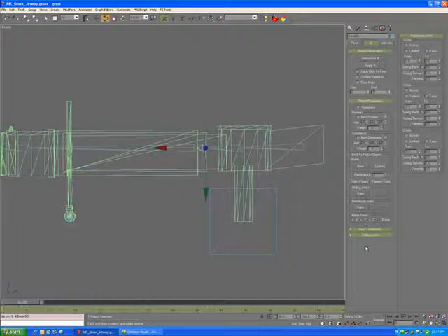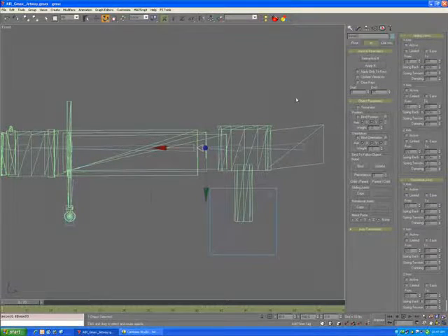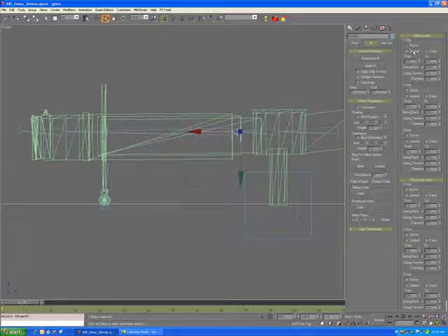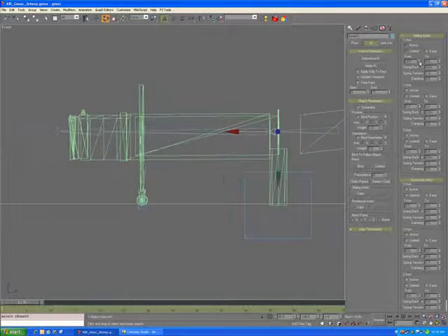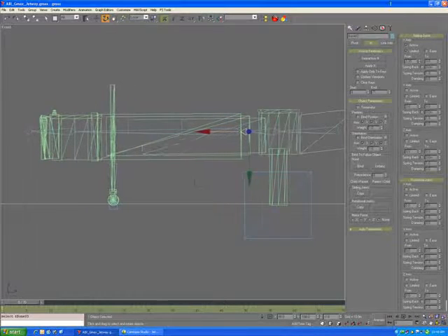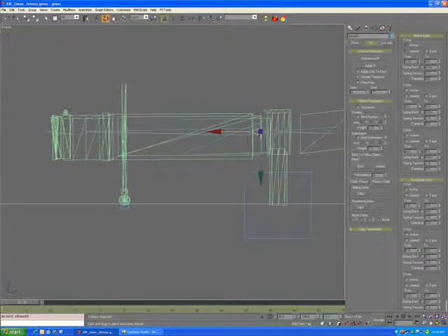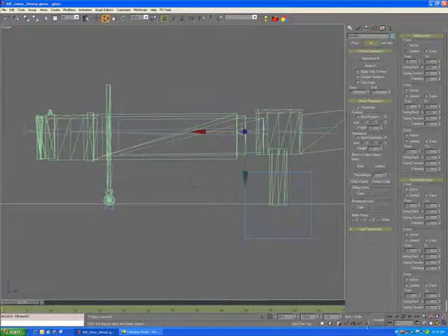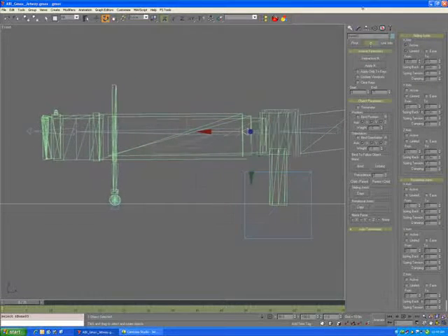So the first thing we'll do is we'll turn off the rotational joints, because we actually don't want these to rotate at all. But we do want them to slide, and we want them to slide along the x-axis. So we'll turn that on, active and limited, and here's where you see where things will get crazy. When you test your sliding joints with skinned meshes in bones, they fall apart, as you can see. However, this doesn't affect your mesh in the long run.